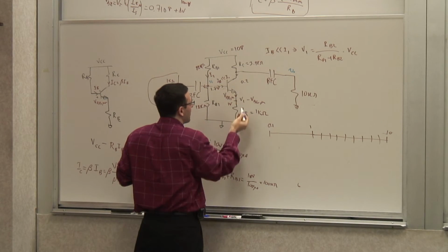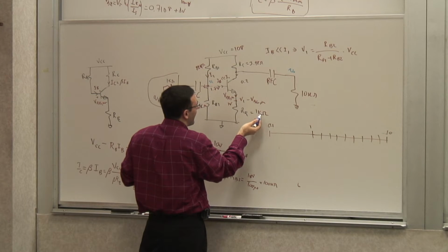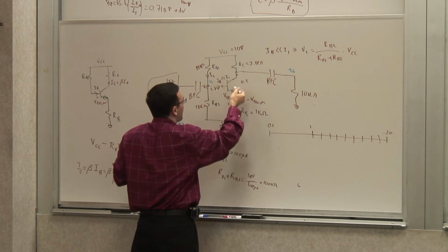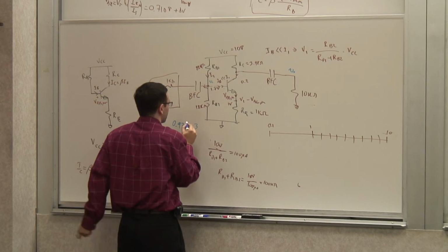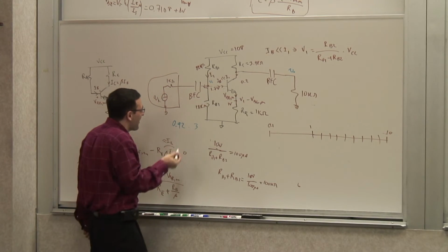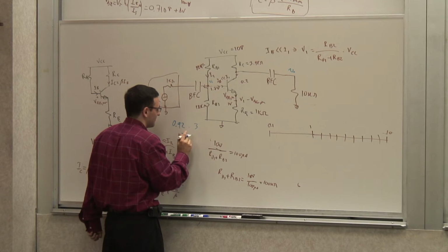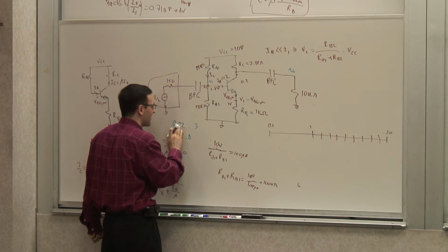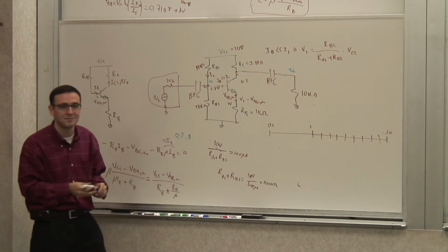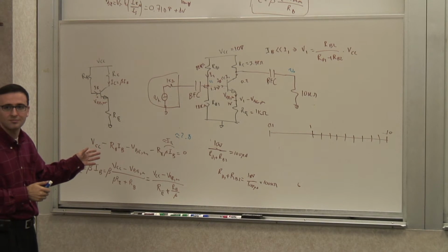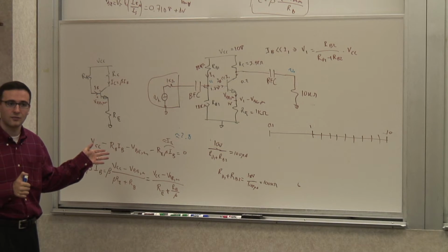3K divided by 1K plus something, so let's say 1K, so it's about 3. So 3.9, 2.8. I would approximate this gain to be 2.8. We'll see how far off I am. So that's the way I want you to learn to do this, if you can.